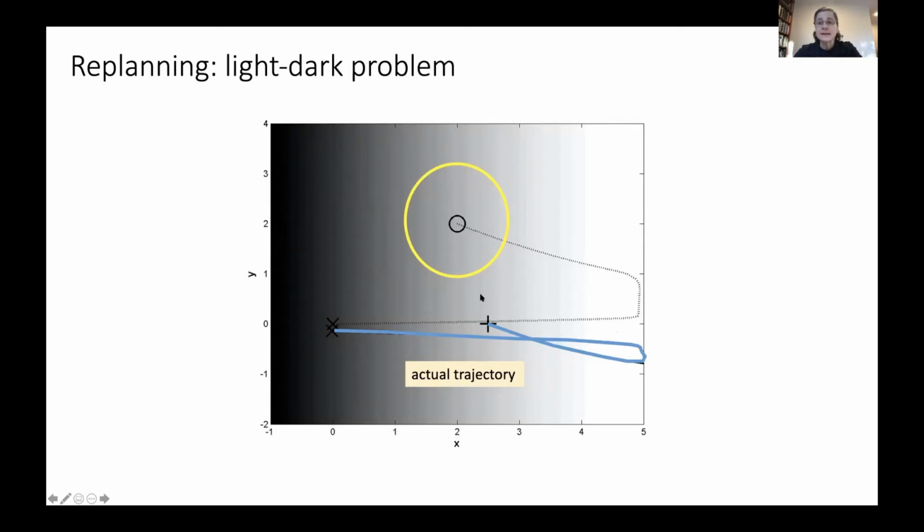and then it gets more observations and it replans a new trajectory. And what we find is that the actual trajectory of the robot is that it starts to go down, but as it goes down, it's going over here and it's getting better and better at observations. And now it's realizing, actually, I'm down here, I'm now below where I wanted to be, and it comes back and it runs back to where it needs to be. So this idea of determinizing planning in belief space has two important properties. One is that it still forces us to gain observations, but the other one is that we can use classical planning, deterministic planning strategies.